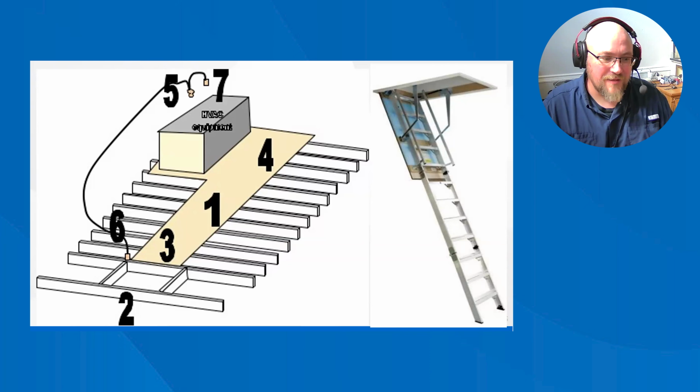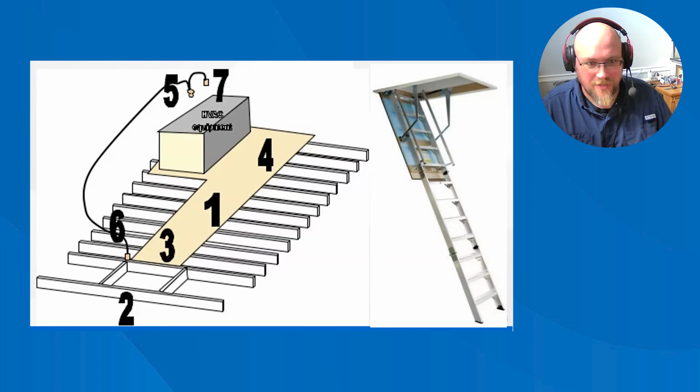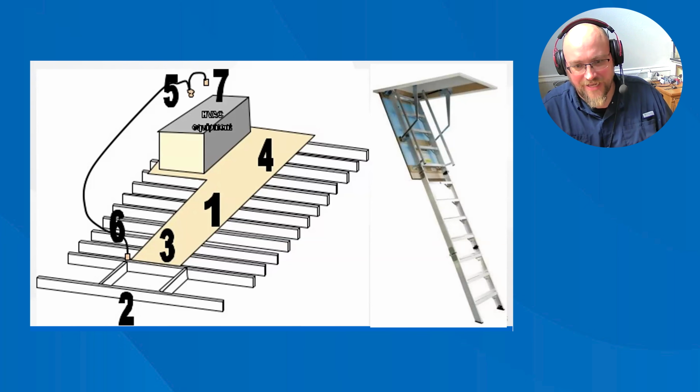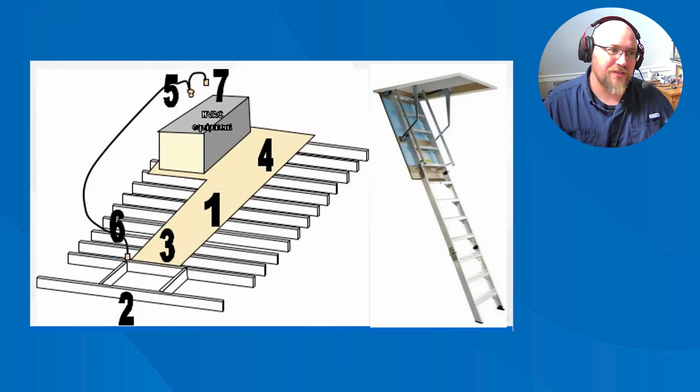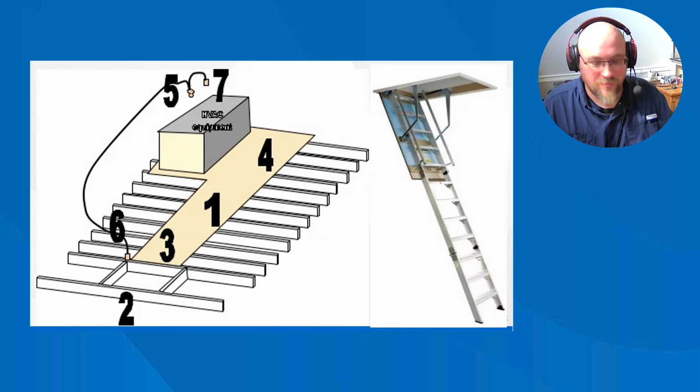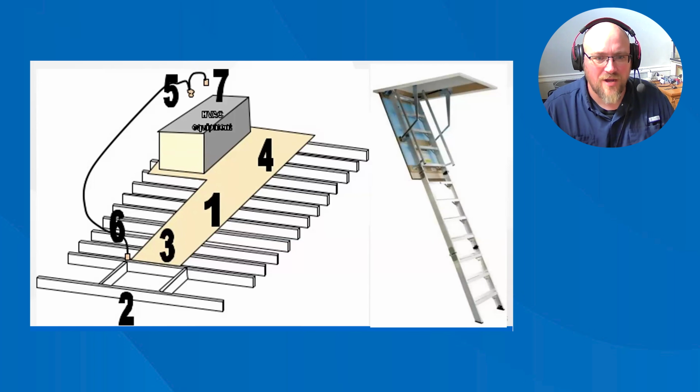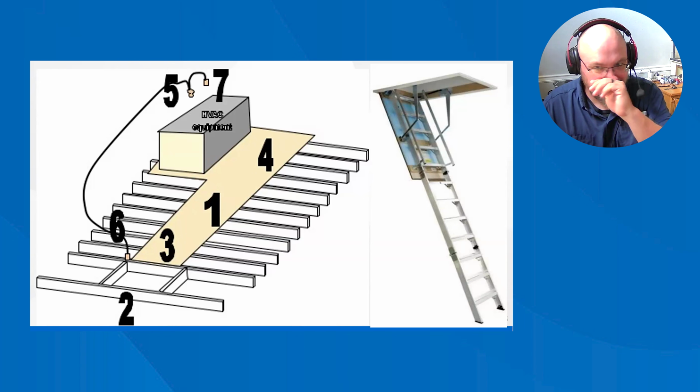So for a long time our local code inspectors did not call out the interior attic pull down stairs being installed in the garage attic or the garage ceiling. That needed to be fire rated. So that has since changed. It's been about 5 years since our local code inspectors started calling that out. So we are seeing that a lot more often, but your area might be different.